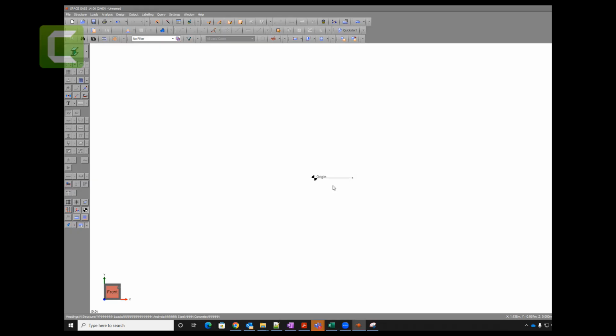So this is a 3 meter member that we just drew. From this point, this is 0, 0, and this is 3. This is another point. Unmute yourself if you fall behind. What have I done? I clicked draw members. I did not do anything else. I pressed 0 on the keyboard, kept it horizontal, and pressed 3 on the keyboard to make it a 0 to 3 meter long member, which is exactly the same as what you see. Now we draw the next member.